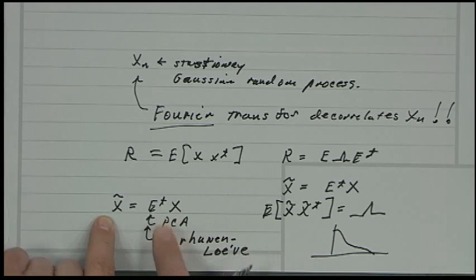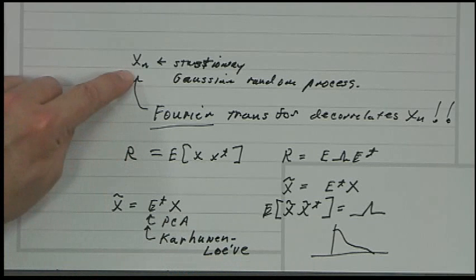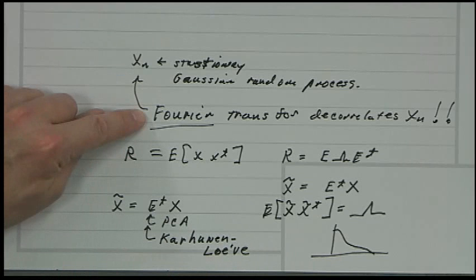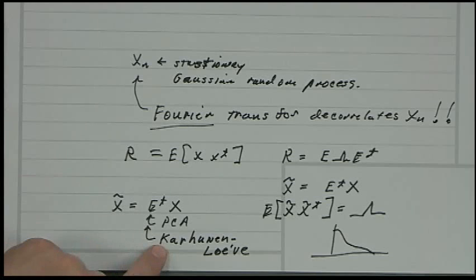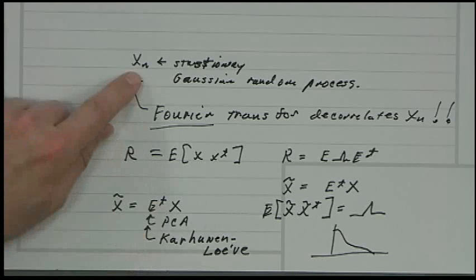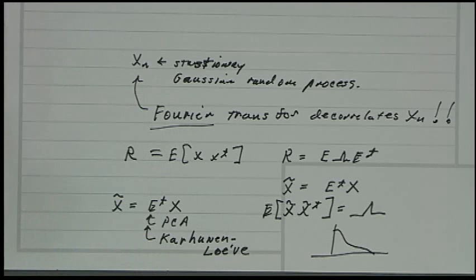So for a stationary random process, the decorrelating transform is the Fourier transform. So the Fourier transform is a good approximation to the Karhunen-Loève transform for any stationary random process. That's the amazing result. That's why the frequency transform is so important in compression. If you give me any stationary correlated random process, speech, image, as long as you want to approximate it as stationary, then I could decorrelate the data by taking its Fourier transform, a frequency transform.